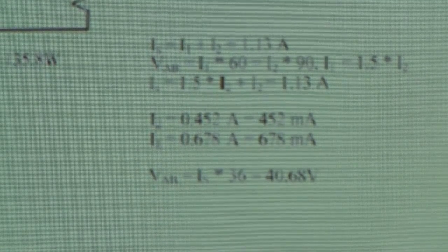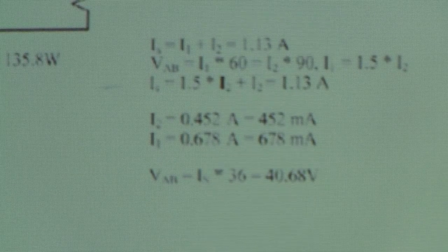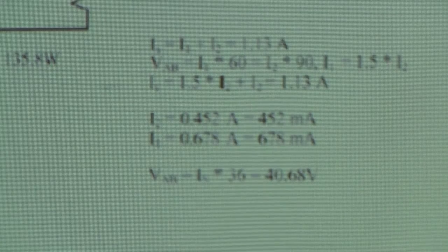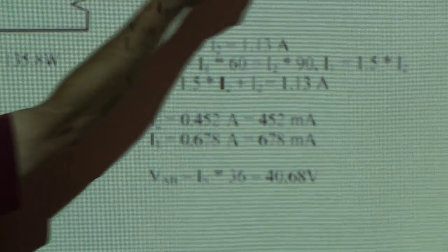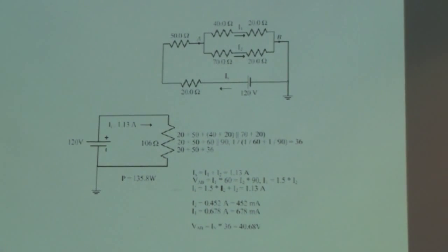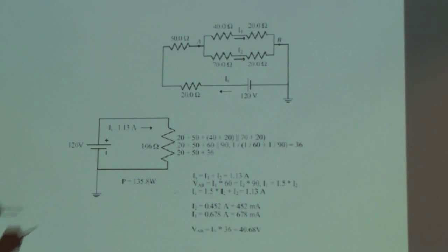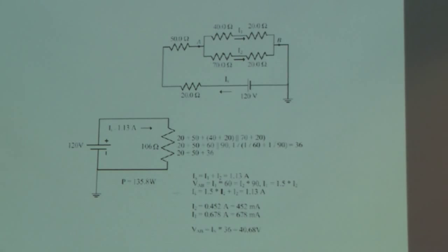So this is how you solve a basic passive circuit. If you want to solve a circuit, what you need to know, at any node of interest, is a potential relative to a reference, and here I've designated it as the lower side of that power supply. And I need to know the current through any leg of interest. So I've completely solved this circuit. Now, this is not to say this is the only way to do it, certainly. You can attack it from different directions, however you want to do the math. But this is a good outline that shows the final answer.